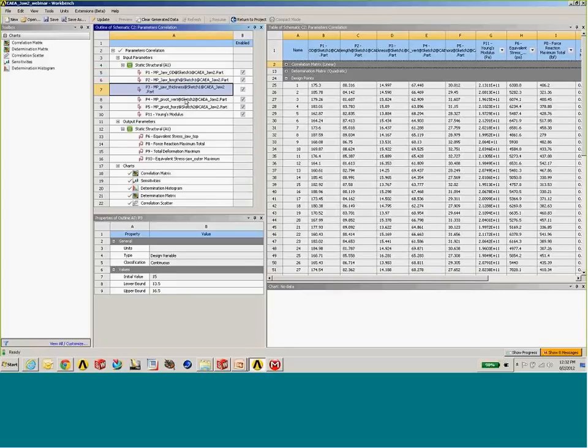Next, I go to the individual parameters themselves, and specify the range, the upper and lower bound that this parameter could potentially see. Now, this is actually a very important part of setting up a robust parametric model, because you're not necessarily guaranteed that a particular design point that you've specified with a particular parametric value is going to regenerate on the CAD side. One thing that you can do is go back to the CAD tool. You can evaluate your upper or lower bounds of your parameters to make sure that they regenerate.